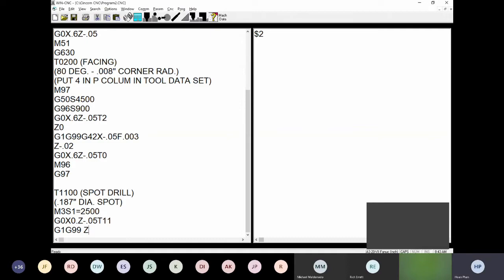So right here we wanted to make a little bit of calculation. The hole is going to be 166. So the hole is 166. We want to put the chamfer maybe 10,000. So 10,000 on the Z, that means we're gonna have 20,000 on the X. That means the finished diameter we're gonna have is 186.